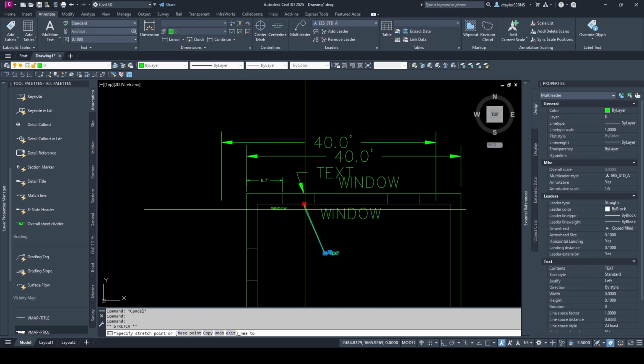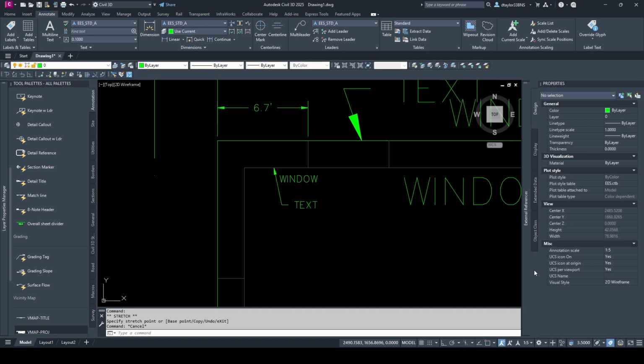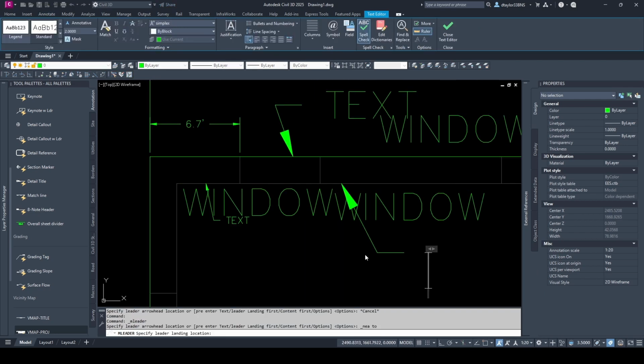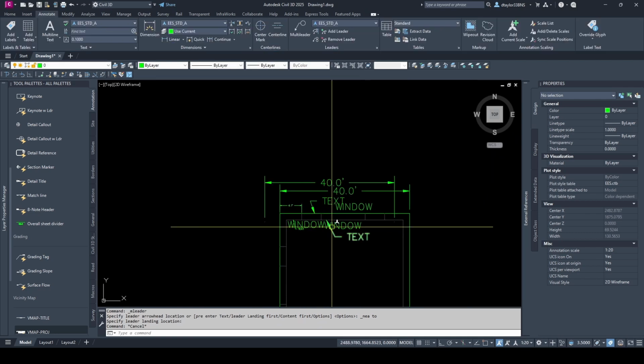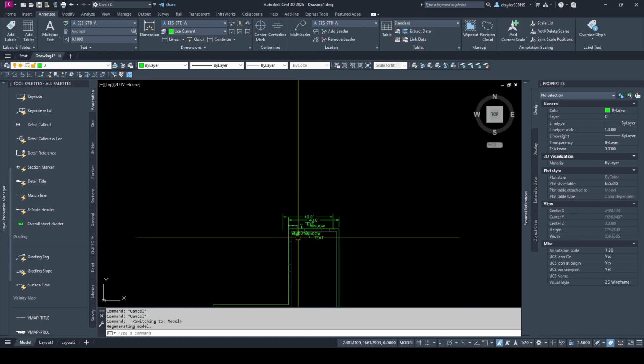That's set to 5 scale. And then let's change it to 20. And it automatically comes in at the right size. And then in paper space, again, the viewports are selecting what they are showing dependent on the annotative scale of the object. Okay, let's move on to blocks.